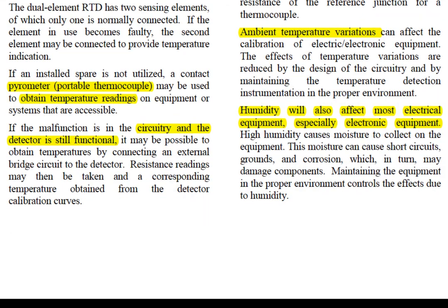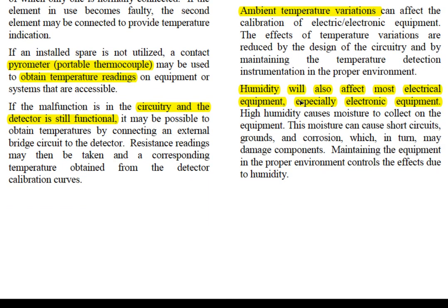The second thing is humidity. If we have high humidity, you know that a lot of moisture collects on certain things. That moisture that collects on, say, hot steel or casings of the equipment will condense. That moisture will drip down, causing a temperature deviation between whatever it's measuring and the chassis or the output or the housing of the detector itself.